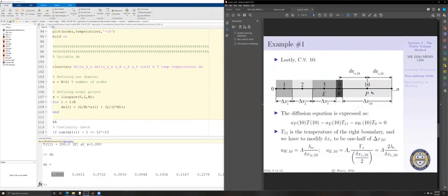And we can see this in this picture. This 10th control volume is actually 3 times longer than this control volume. So delta x1 has a length of 0.05 meters. Delta x2 has a length of 0.0611 meters. I actually drew this to scale. Delta x3 has a length of 0.0722 meters, all the way through. So we have a non-uniform grid spacing.